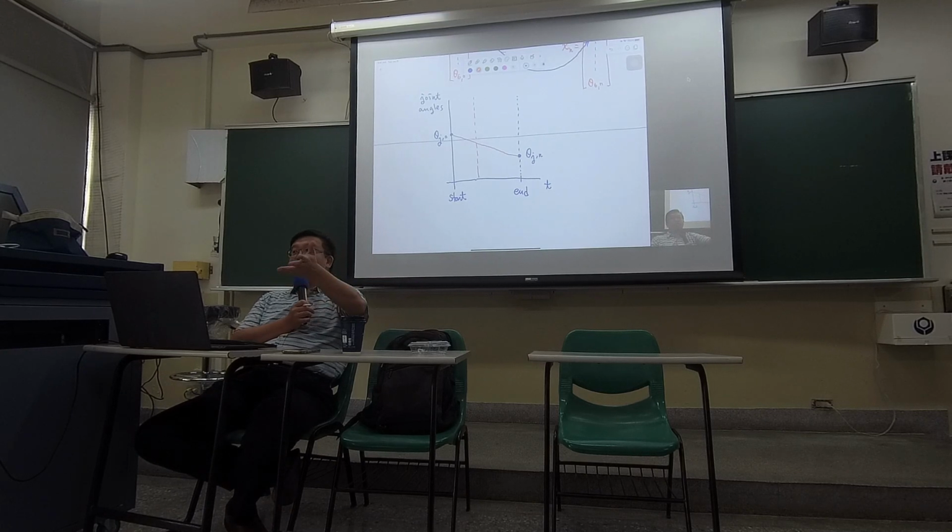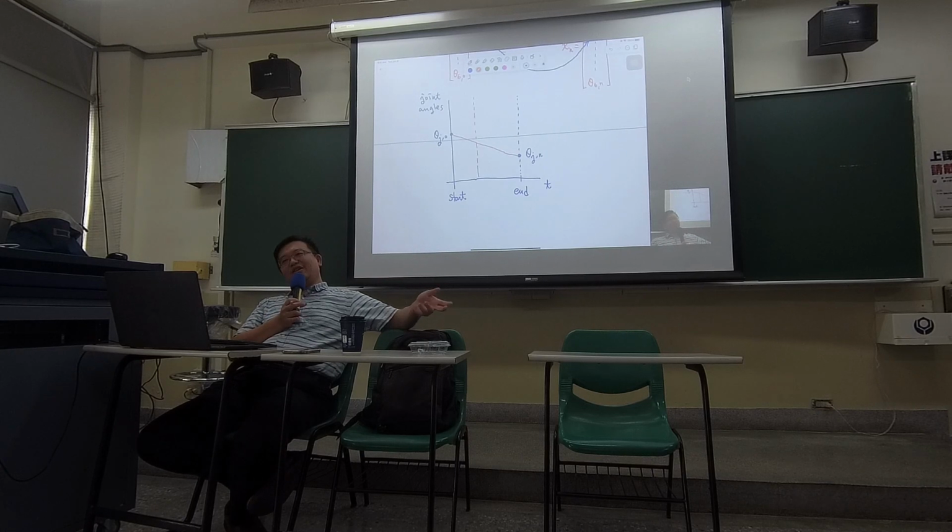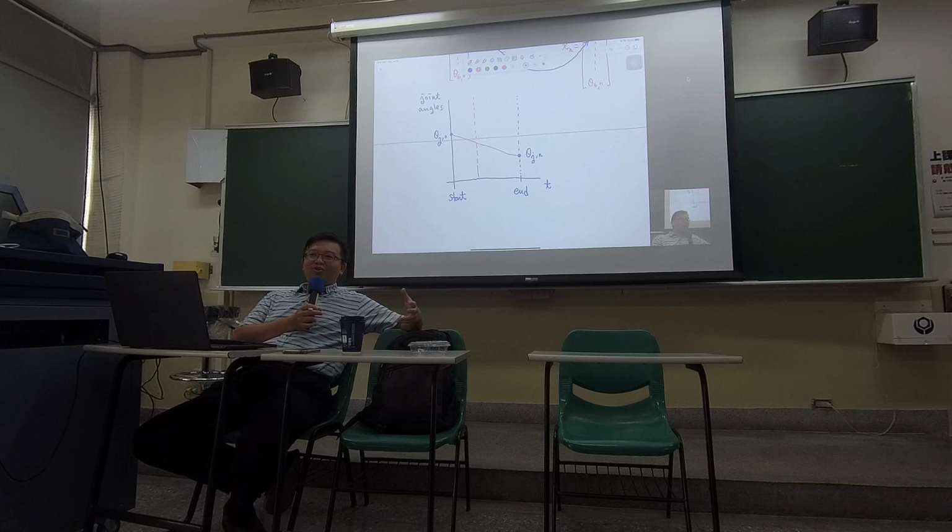You guys took the homework, right? Inverse kinematics is harder than forward, more complex. Forward kinematics is like plugging in some equation, a bunch of transformations, boom, you get it. But when you solve inverse kinematics, you may have multiple solutions. You need to figure out a way to determine which one is the right one.